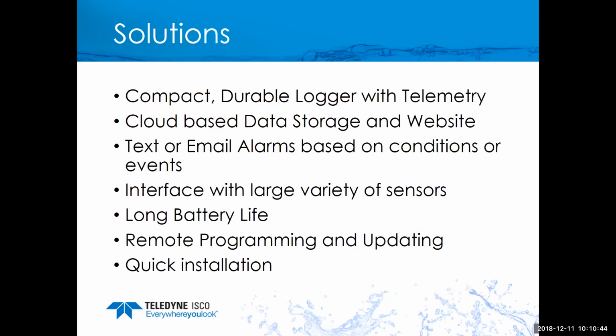Now, as for solutions, something that most companies or cities would be looking for is a compact, durable logger with telemetry, meaning it has access to push data to some location or send messages, so that the operators are able to monitor and react to that data. Some sort of cloud-based data storage with a website would also be necessary, as well as text and email alarms based off of conditions or events to help the operators respond quickly to developing problems or problems that already exist.